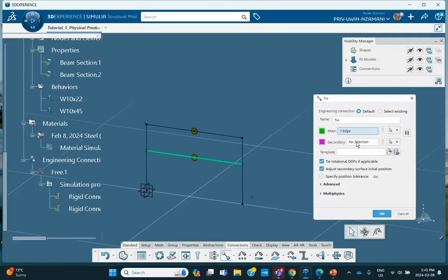And for the purple, I select the things that are connected to, and they're going to be tied together, tied to that horizontal first floor. That guy and this guy. Okay, now notice that I did not check this. And you will get an error message. We have to come back and check this and put a dummy tolerance here. You say, okay, no problem there.